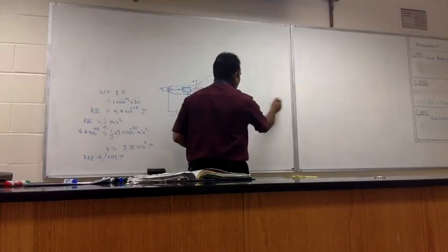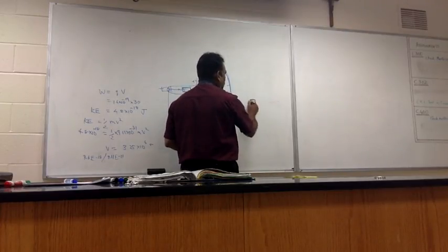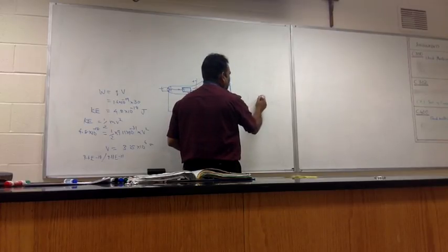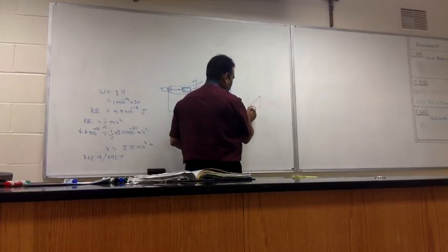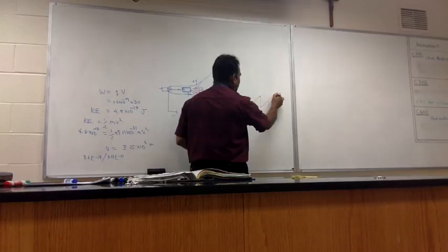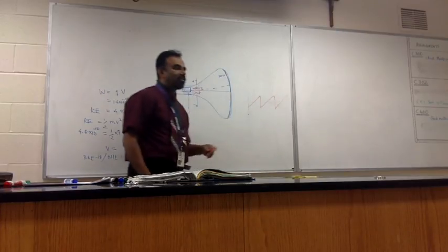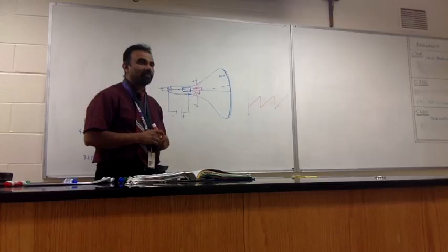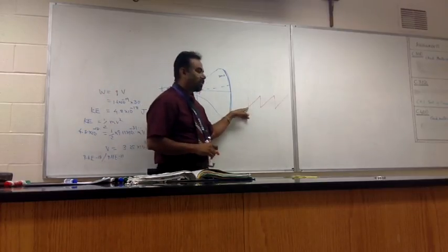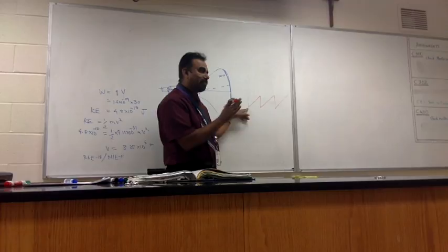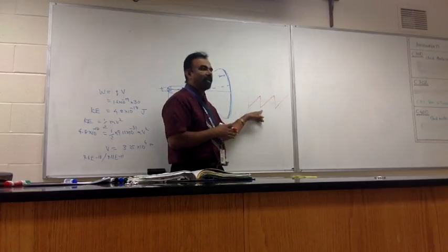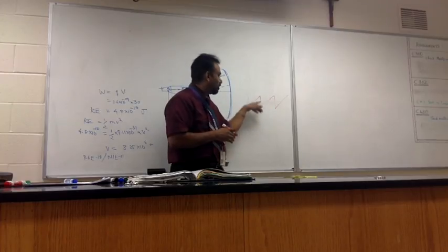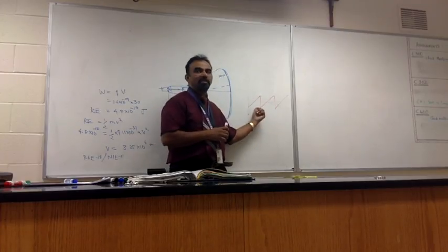The signal goes up like that, or from here, it goes up, and as soon as it reaches that side, immediately it flips back to the same old value and then goes again. So that is alternating, but is alternating in a very special style. What is a special style? The voltage actually is going from a negative value to a positive value, and all of a sudden starts over again from the negative value to the positive value. So this is a flyback. We call this signal a sawtooth signal. Sawtooth.